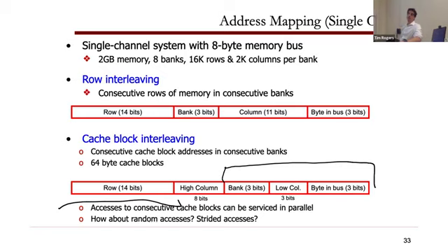Yeah, I mean, it's poor for energy if you can actually get it from the single bank. But if you think about it, lighting up the first one, consecutive stuff, you're depending on it being on one row, and you get 1 row worth of stuff ready. If I stride things across the banks, I get 8 rows worth of stuff ready, right? And that's the win, that it's ready sooner so you can keep the pins active longer, because there's 8 times as much data, but obviously that's costing you energy to keep all that state. Make sense? Okay, I'm going to move on from this.